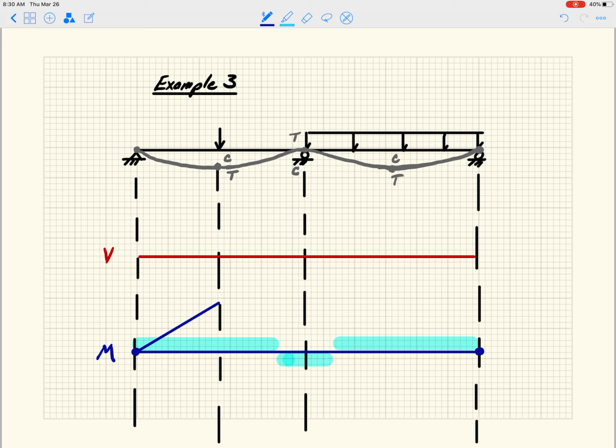And so the only way for this to work and be plotted on the top side of the member is to do something like this, right? Right. So that is consistent with the point load, right? It's linearly varying, and then it has to cross 0 where we see the deformed shape go to concave down from concave up. Right?